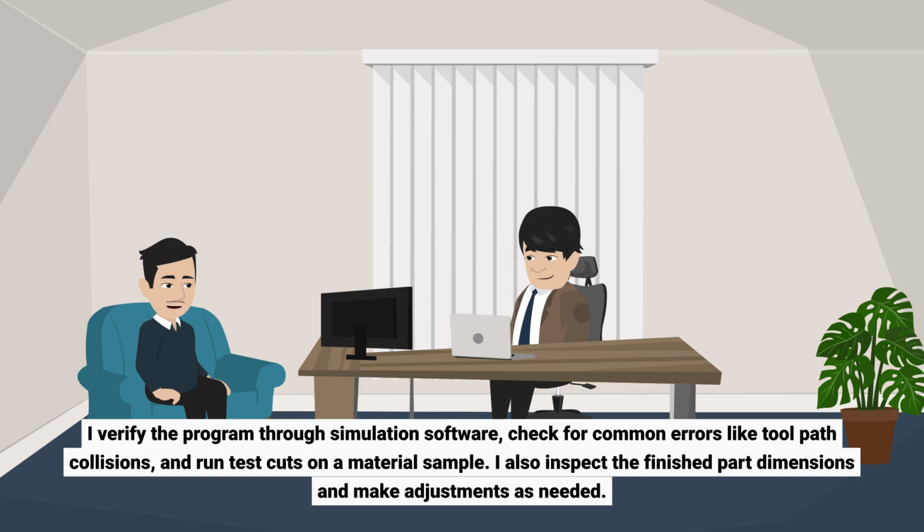How do you ensure the accuracy and quality of a CNC program? I verify the program through simulation software, check for common errors like toolpath collisions, and run test cuts on a material sample. I also inspect the finished part dimensions and make adjustments as needed.